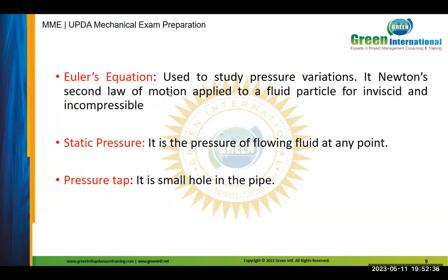These cases here show three types. The first one is the orifice. The second one is the venturi. The third one is the nozzle. The three types here measure and calculate the velocity with the same concept. What is this concept? I just need to measure the static pressure at two different locations or two different positions. These two different positions are at two different diameters.